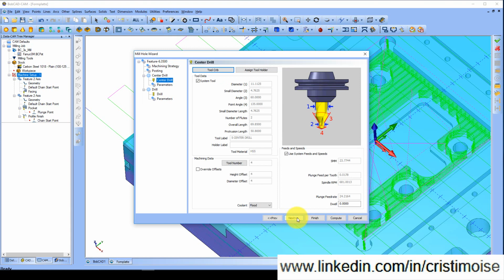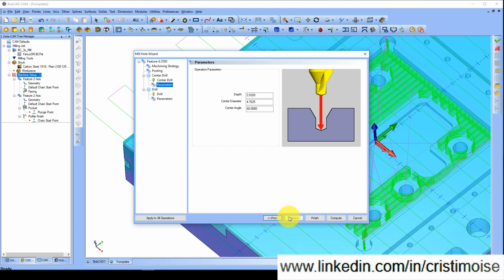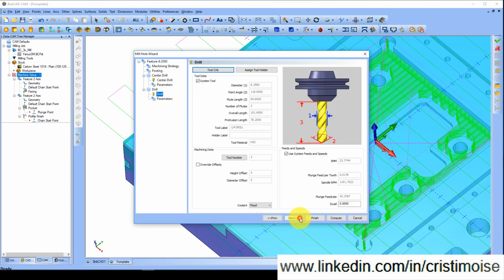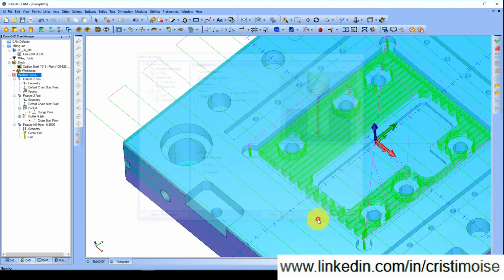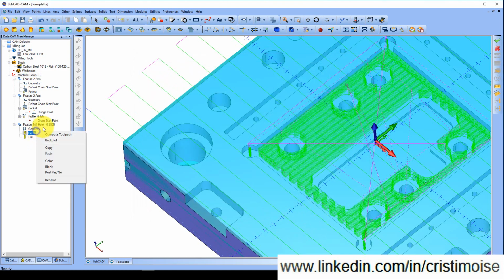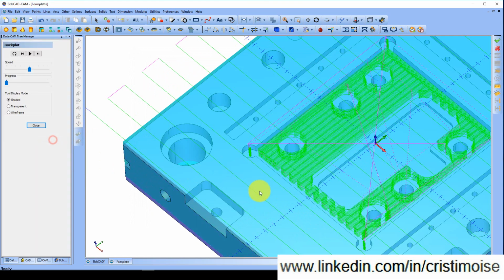Yes, but right now, if I put there the hole diameter, it will be a good feature to automatically generate the right tool for me. So I will put here the good diameter. I do not want the center drill, but it already generates a center drill for me. I think I can delete it. It's no problem. It's not an issue. Yes, I will leave it like so.